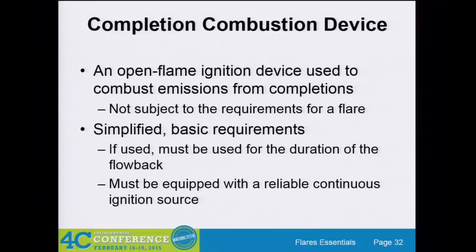The ignition device used for combustion of emissions from completions is not subject to the requirements of the flare I just mentioned, and must be used for the duration of the flowback and must be equipped. This is important, so it should be underlined. There's a lot of debate in the industry. We have had flares out there for decades. Spark ignited or high energy reignition are specifically not allowed in Quad O, and you've probably seen the FLIR VOC camera video of the flares out in the field, with this huge plume coming off of them.